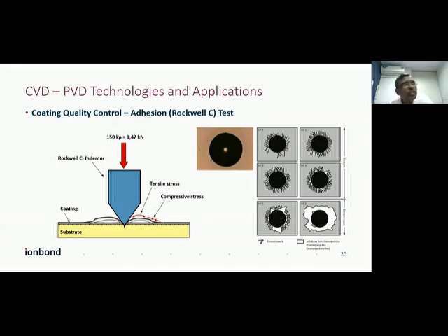It is a good question, and directly related to the quality as well as the cost. Now, basically, with the coatings, by and large, the life improvement in the forging industry is from 50% to 200%. Because for some applications where the forged component is smaller, where the impact is less, we can go to even 200% life improvement. And where the big components are there, then it may be in the range of 80 to 100%.